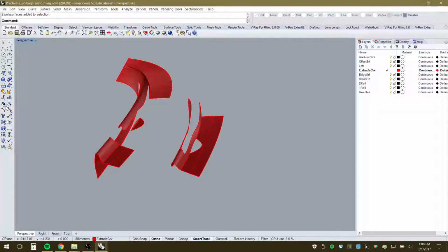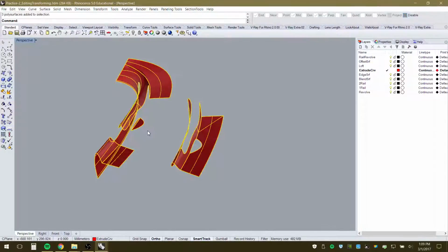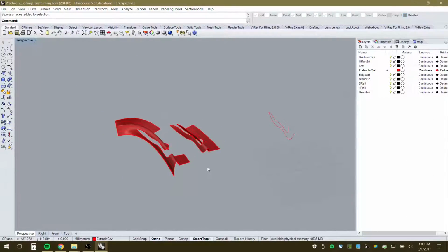The way around that is just to add to the group. So select objects to add. I want to add this object, right click, select the group, that's the group, and that's done. So now it's all one group. So again, that's handy as your models get a little bit more complex.